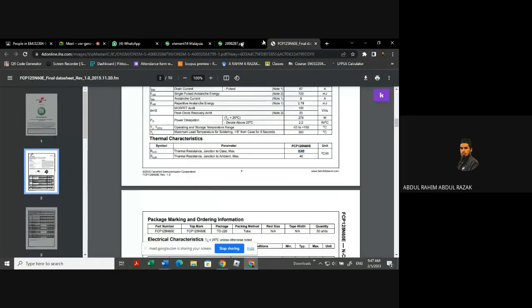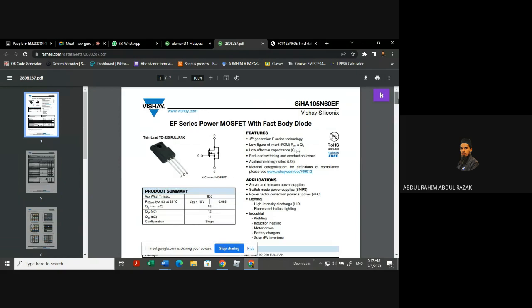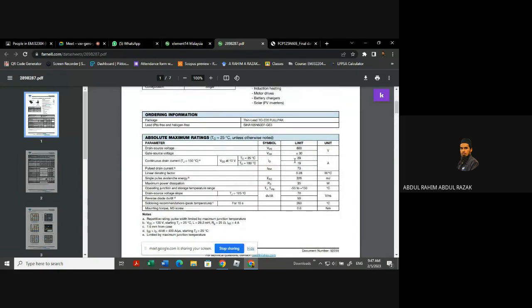The first thing is that we have to consider how much the system or the switch can operate without a heatsink. That has to be considered first. Let's say we have here the Vishay part, which can extend up to a drain current of 29 ampere. When the operating temperature is up to 100 degrees C, you have to derate it down to 19.